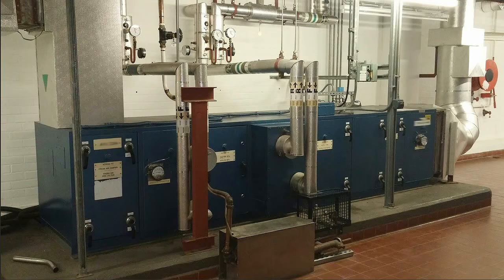Now, to open up the AHU, you're going to need to open some of the panels up, the access panels, which are purposely there for that exact reason, so you can climb inside and have a look or fix or change the filters, change the belts, etc. So on the AHUs, on the panels you can access, you'll see these handles here. You might have handles, or it might just be a panel key fitting. In this instance here, they've got the panel keys there, so you would undo these and just lift those off, and in this case you would just turn these and that will undo the hook, and that will allow the entire panel to come off.